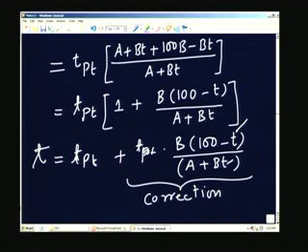So, what we will do is assume that this temperature can be approximated by the platinum resistance thermometer scale, which is indicated by T_PT. Number two, we will assume that in the denominator the term B T is not as important as this term, therefore we will neglect B T in the denominator. If you do that, you will get a very simple expression for the resistance non-linearity.